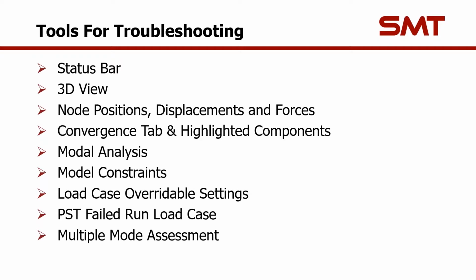And also it's worth noting that if your problem in MASTA is in an advanced analysis mode, then the problem may be lying further back down the line. It may be down to a power flow issue. It may be down to a system deflection problem. It could be any of those. So it's well worth double clicking on the status bar and going back in the chain to find the analysis where the model has actually failed.